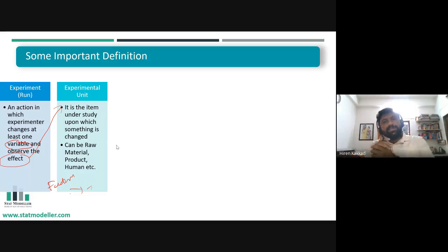One senior faculty was there with me, who had quite some experience of this Taguchi experiment implementation. So in that, what is the experiment? We have given them a plan, like the first experiment: speed 1, speed 2, then pressure 1, pressure 2, pressure 3, cooling time, and so on. There are so many factors. Here each should be at low level or high level, and all these low and high levels were defined by conducting brainstorming and using the historical data that they have.